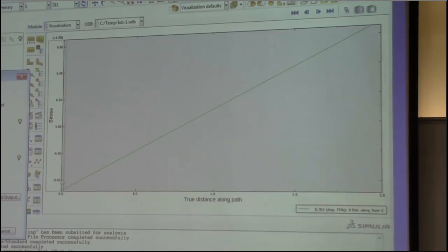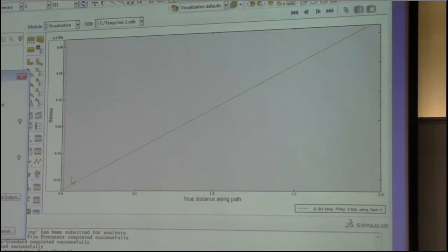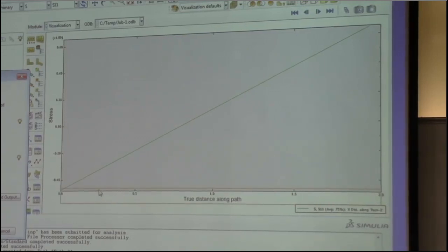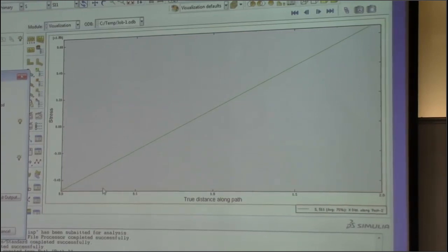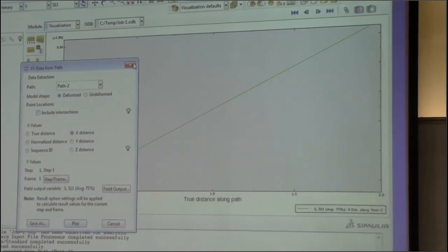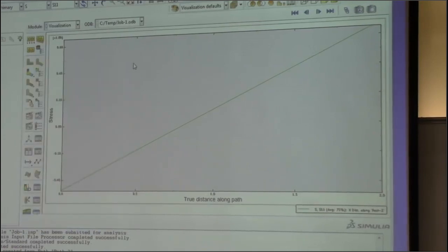So the true result should start from here and decrease, decrease, decrease, and then increase. So this should be the minimum result, right, around here. But if you only use one element, you will miss this minimum result and the result will not be accurate. That's why you need to use your background knowledge to determine how many elements are best for your problem.